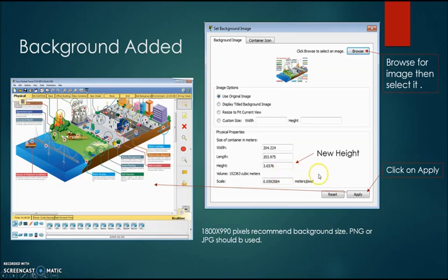You can also add whatever height. So in this case, if this was really outside, I'd probably change this to 3,000 meters. That way we would have a 10,000 foot elevation in the United States. So again, when I do this, I do need to click apply in order for this to happen. One of the best ways to learn how to do this is to go ahead and open up a sample file, add a background, and have some fun with it.